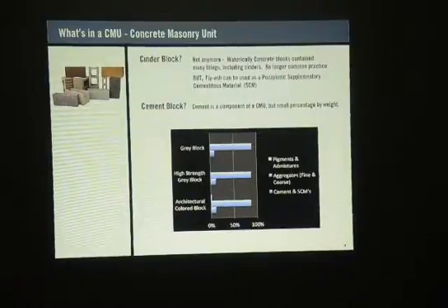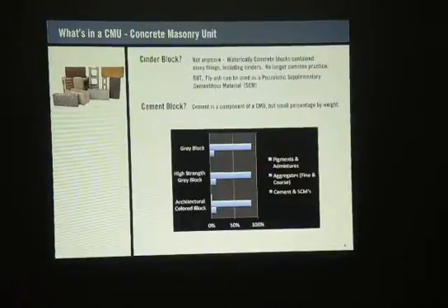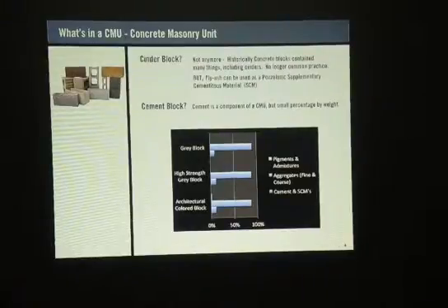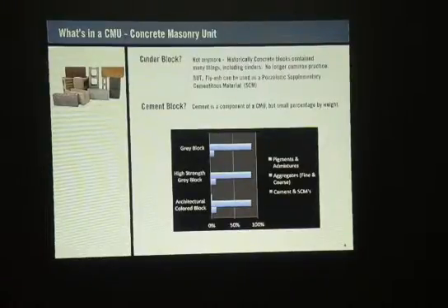The other thing I want to pass around, I'm going to give this to Mo, is on this side, this is called precision, okay? Normal gray block, I think I mentioned this earlier, is 10% cement. So you say, well, Mike, what is poured in place concrete in its cement content? It's actually 13 to 15%.